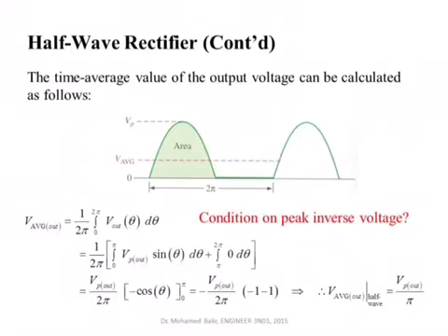Now I would like you to see that when you get a signal like this one, you immediately ask what is the equivalent DC voltage. If we have the same DC voltage over the whole cycle, what is the value of that DC voltage? What is the value of this average voltage? It turns out that this average voltage is simply the area under this cycle, divided by the length of the total cycle. So we simply apply an average expression. We integrate over the whole cycle from 0 up to 2 pi, and then we divide by 2 pi. This will give you the corresponding equivalent DC voltage.